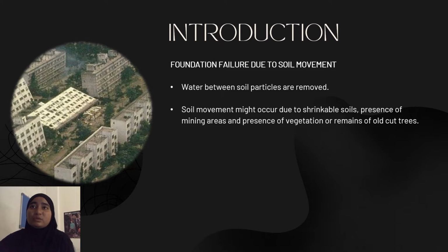Foundation failure due to soil movement might be caused by the water between soil particles being removed, and soil movement might occur due to shrinkable soils, presence of mining areas, and presence of vegetation or remains of old cut trees.